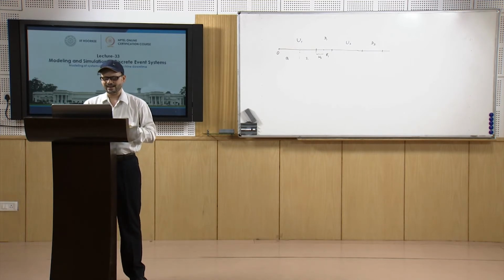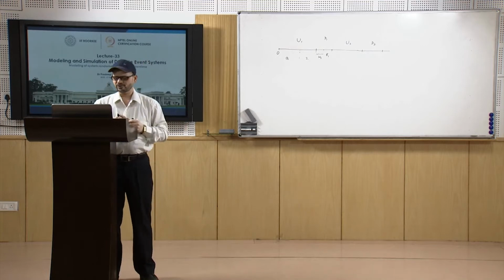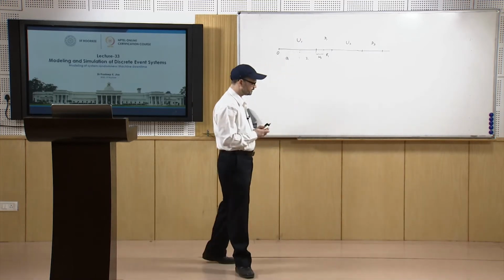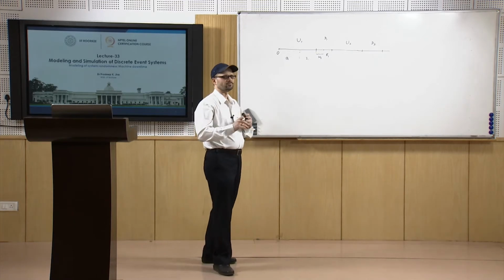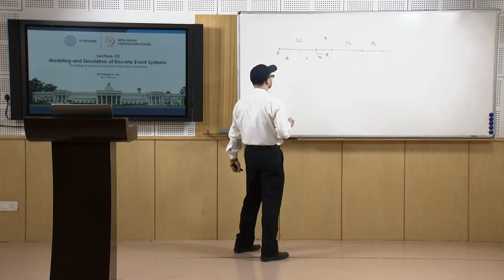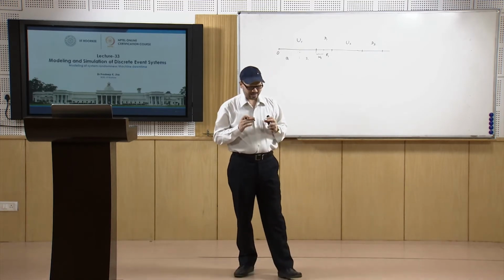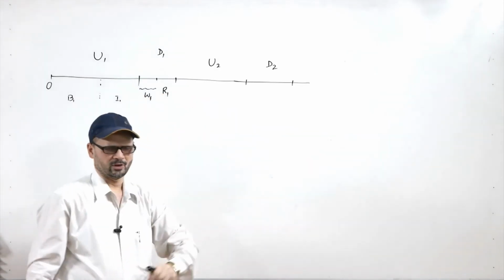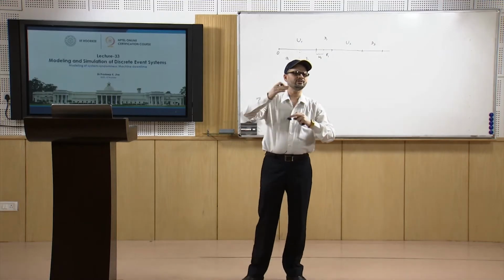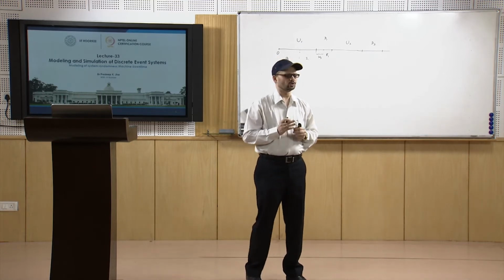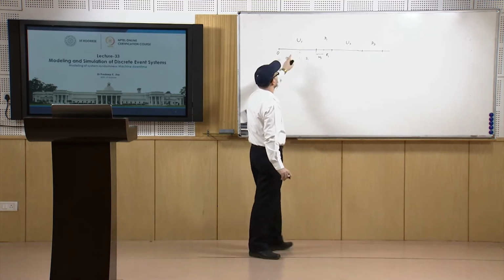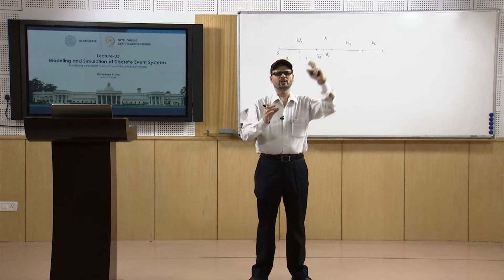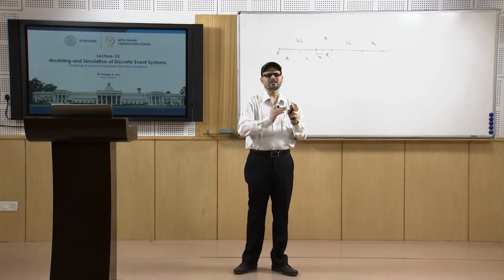Now, you have to model these machine up segments or down segments. So how to model it? For modeling these uptimes, there are approaches that are followed. One of the approaches is the calendar time approach. The calendar time approach talks about the time of occurrence of this uptime and downtime. In the calendar time approach, once you have these data available from the distribution functions, you know that the machine is up for the period of u1 time, and from u1 to d1. So it will take the value of u1 from the system and it is up during that period.